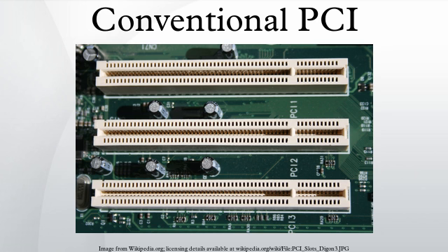Each PCI slot gets its own configuration space address range. The registers are used to configure the memory and I/O address ranges devices should respond to from transaction initiators. When a computer is first turned on, all PCI devices respond only to their configuration space accesses. The computer's BIOS scans for devices and assigns memory and I/O address ranges to them.